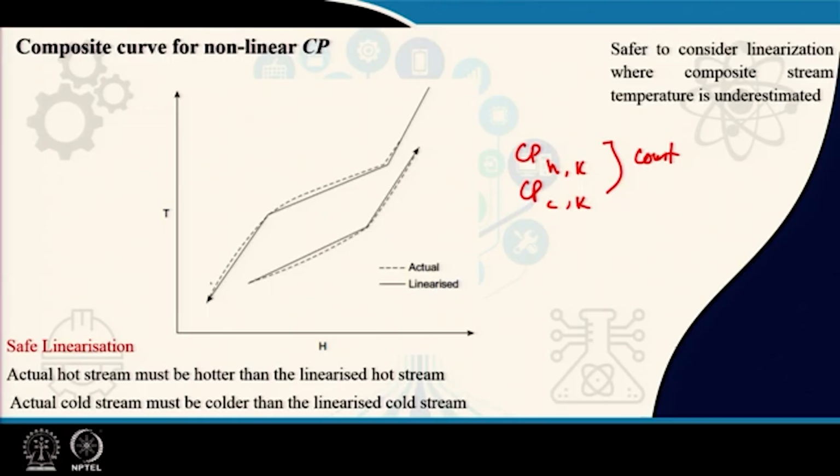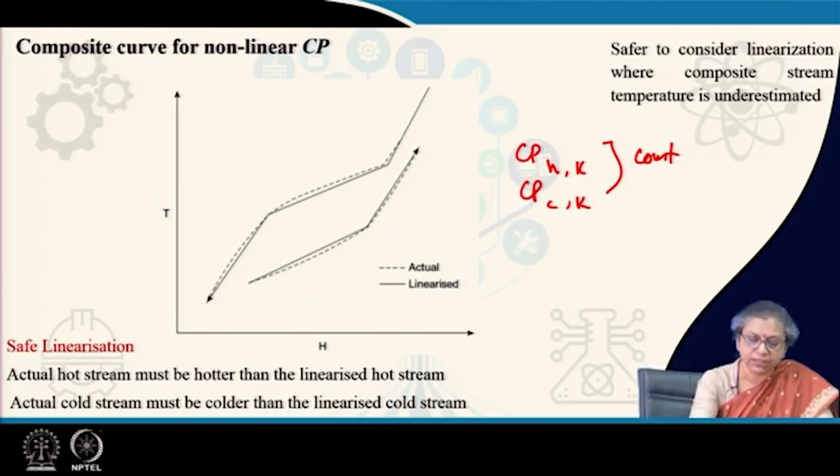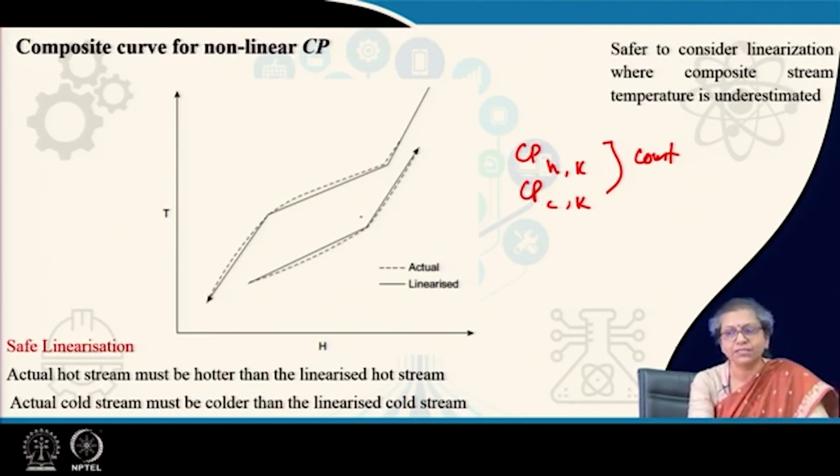What we do is simply break the non-linear curve into small segments which are linear, right, and then we perform the pinch analysis across these curves. Now, when we are breaking them into small segments, for a safe design it is very important to ensure that the composite stream temperatures are always underestimated.